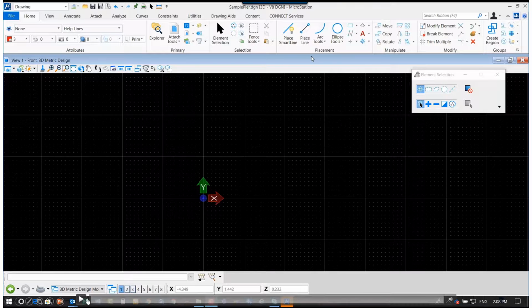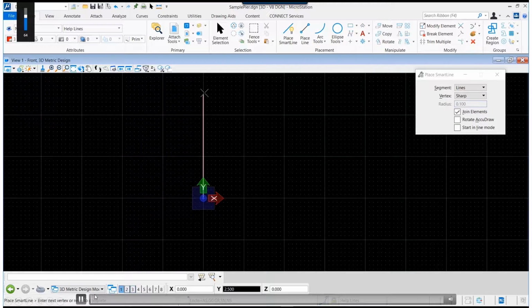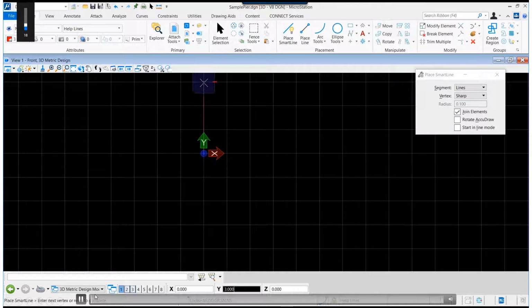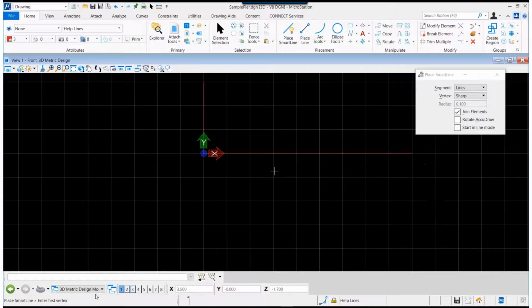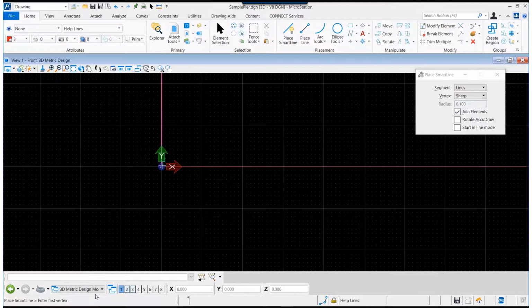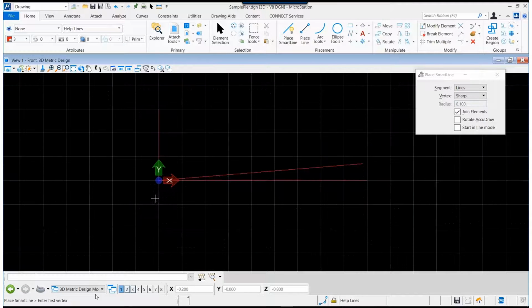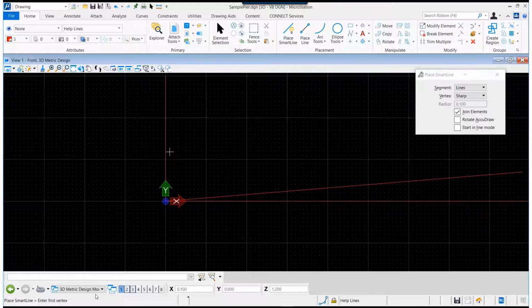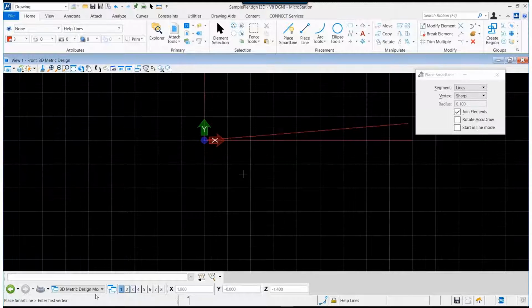So as I said before, you just start with 2D drafting, right? So you start drafting this and you can make use of helping lines, help lines as we call them, because they will encompass the elements that we are going to generate. Also I use this slope line because, remember, my cap I will like to rotate according to the superelevation. So I will use this element to adjust the rotation too.